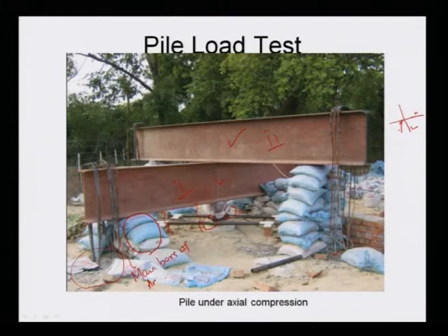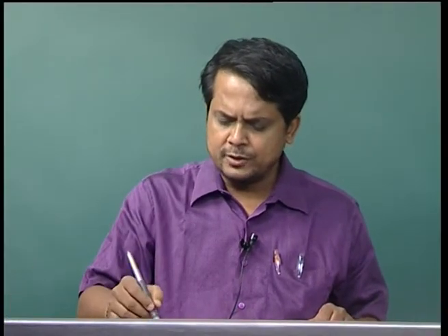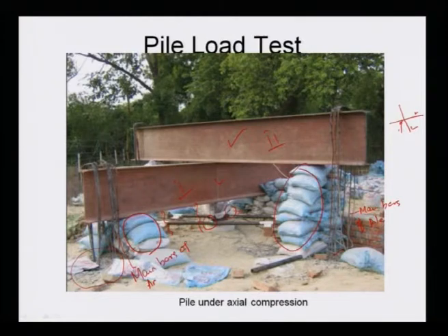After placing this, in the same way you can place the girder. Here also the main reinforcement, the main bars of the pile, are tied with this girder. These girders have been placed crossed at 90° to each other, and to make it symmetric, some sandbags have also been placed at both ends of the second girder.